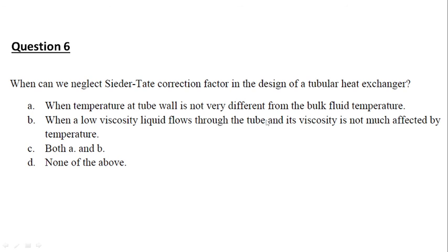You need one temperature controller and one thermocouple in the system. So you need to set one controlled value, like you need to maintain it at 35 degrees Celsius.